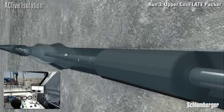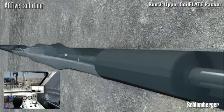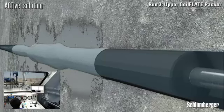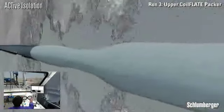Once the downhole load and pressure measurements indicate that the packer has successfully set, a valve will open and cement can be pumped through coiled tubing and the packer. A squeeze for water shutoff can then take place. Tension is applied and monitored at the control cabin to disconnect the upper packer.